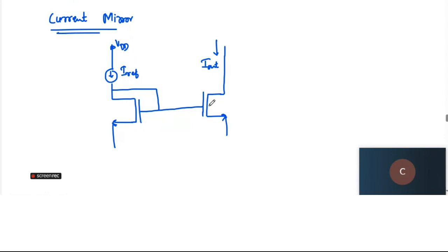Obviously, the body will be connected to the source, which I'm not going to consider over here. Okay, let's write it. It will be like this. Basically, this will be my schematic of the current mirror. When I said fixing up the W by L ratio, I'm going to fix the W by L ratio of these MOSFETs with the value which we figured out just now.